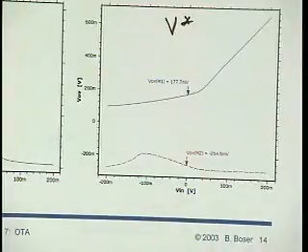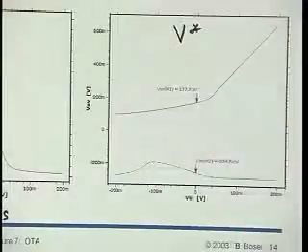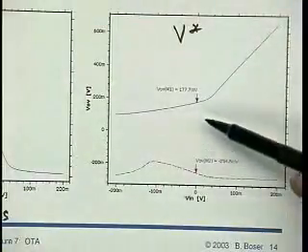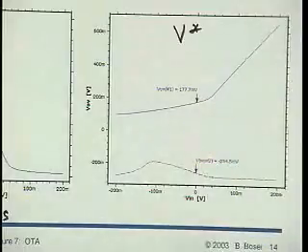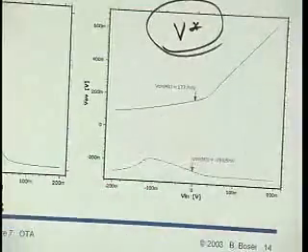Otherwise, again, that hints I've made an error in my SPICE. Very, very tedious, but very useful, and a lot less tedious than finding an error in 200 lines of SPICE spaghetti, right? Of course, we see here also that as we move from the bias point, well, V star is a small signal quantity. Of course, it's going to change, right?